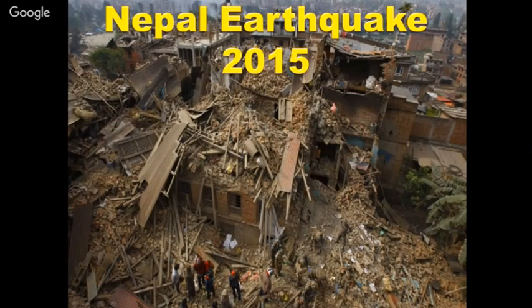Here, I will take the example of Nepal. In 2015, the Nepal earthquake occurred. We studied the different patterns of the waves in the Nepal earthquake. We saw that those earthquakes are of longer period. And as I have already told you, in a longer period earthquake, most damage will occur in single story buildings also, because the fundamental frequency of a single story building is very high, and in case of a multi-story building, the fundamental frequency of the structure is less.